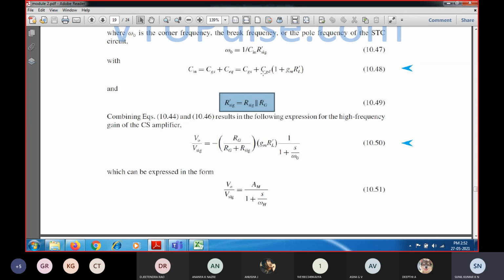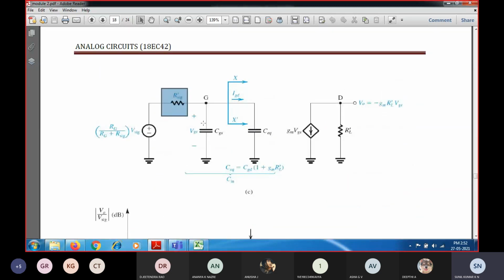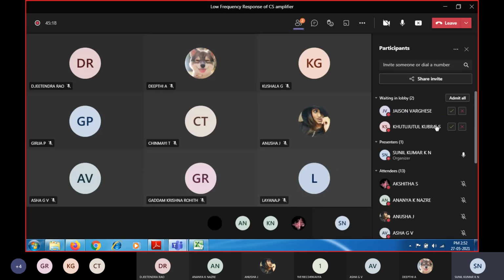These two correspond to a transfer function which is low pass, because you can see one R and C component is there. So this is nothing but a low pass transfer function. Low pass means the lower frequencies will be passed and the higher frequencies will be attenuated, so that you can see there is a severe roll off of the gain as you move after this cutoff frequency.